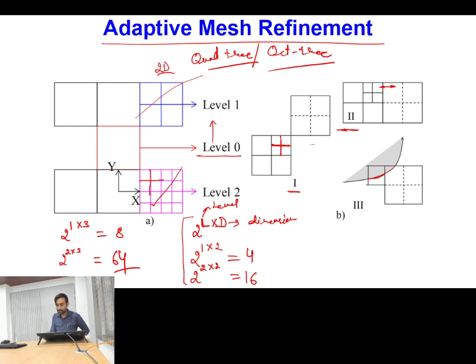Okay, so there also, if an interface is shared by two neighboring cells even in a curved way, then also we have to create this refinement, and of course this point is being taken care of, particularly if we are using the gradient, particularly the gradient of volume fraction.